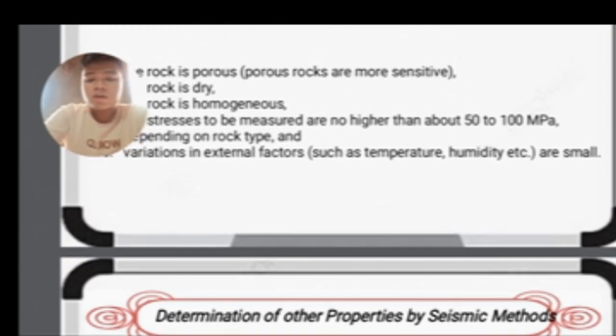It has also been observed that when rocks or soils reach the point of instability as the result of landsliding or some similar agency, the development of fractures is accompanied by acoustic emission. The onset of instability may be detected by arrays of geophones planted in and around the ground. Acoustic emission has been studied for at least half a century, for example by Neil in 1968, and it is used in some mines as a means of monitoring stability.